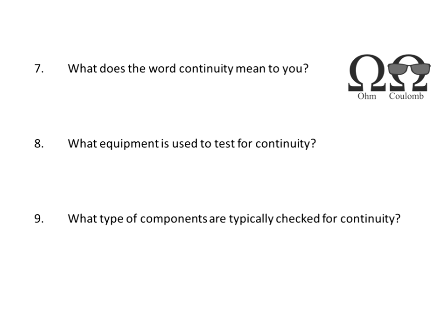Now, what equipment is used to test for continuity? Typically, to test for continuity, you will use a low resistance ohm meter, or an ohmmeter set to a low resistance scale, or the beeping function on your ohm meter. A lot of the good meters will tell you the ohms as well as beep when you do have continuity.